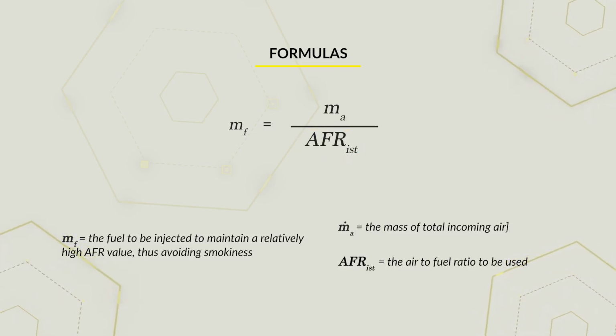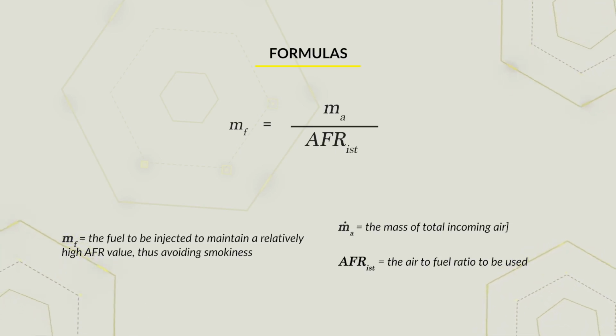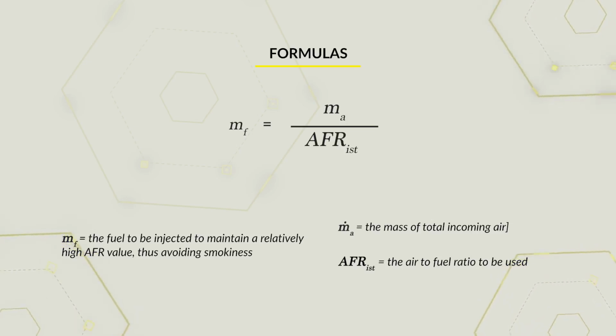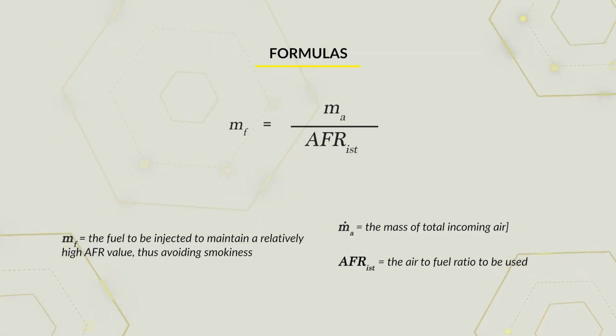Given that this strategy, based only on the engine load formula, is imprecise as it considers data of density, temperature, and standard air pressure, it is necessary to use a formula that calculates the density of the air, taking into account the pressure inside the intake manifold measured by a possible MAP sensor or calculated internally by the ECU, of the atmospheric pressure and temperature of the intake air. Let's take a look at this together.